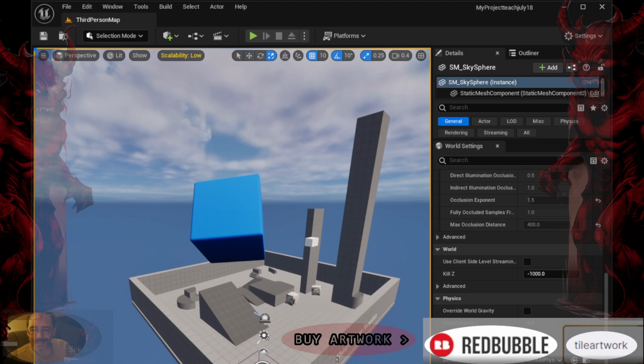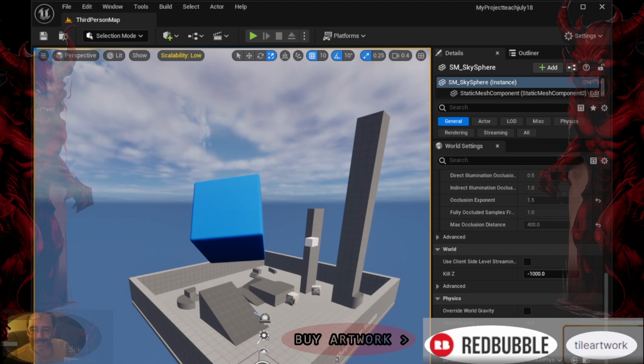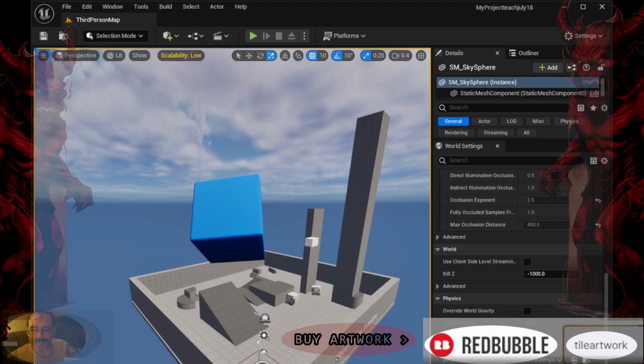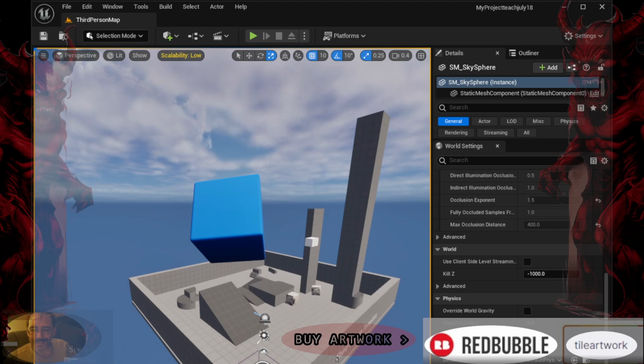Operations. Once connected, you can perform version control operations by right-clicking on assets or folders within the Content Browser or using commands available through the revision control button in the editor's toolbar. Common operations include checking out files for editing, committing changes, updating to the latest version, and viewing revision history.